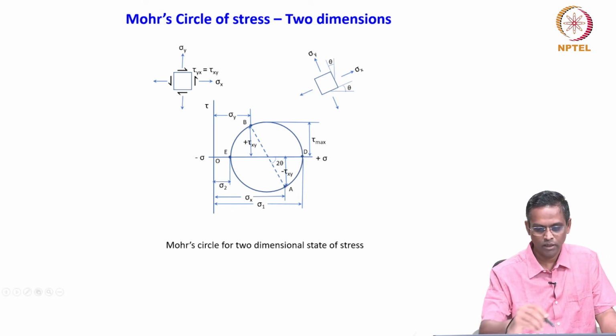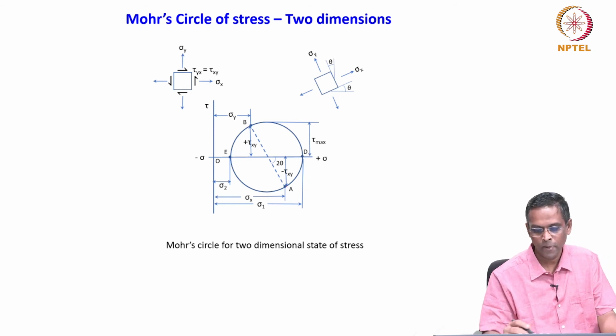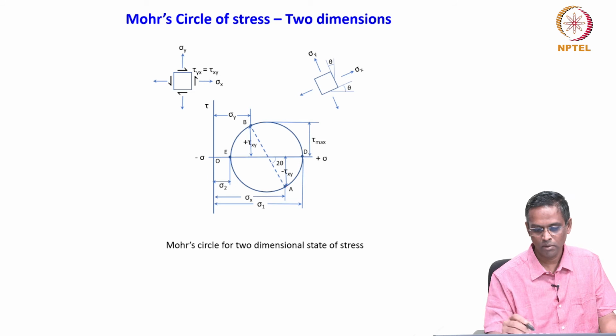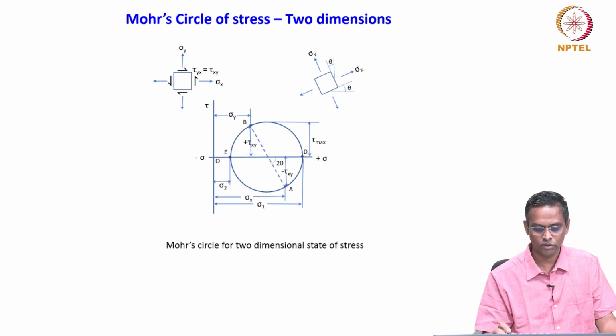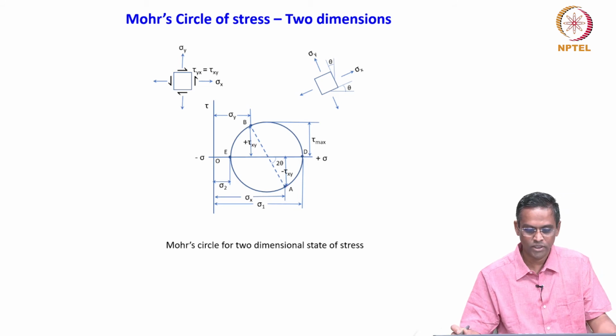Here it is negative shear stress, here it is positive shear stress. Depending upon the rotation, whichever sign we are looking at, we can easily relate this very nicely. You can represent the normal and shear stress for a given orientation. So, that is the usefulness of this state of stress.